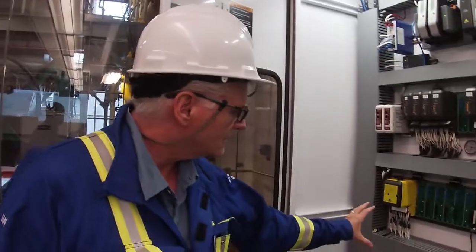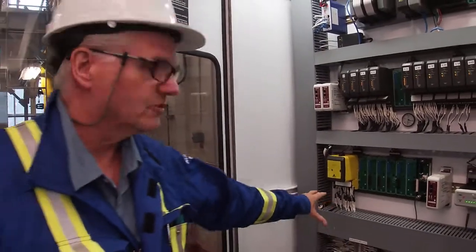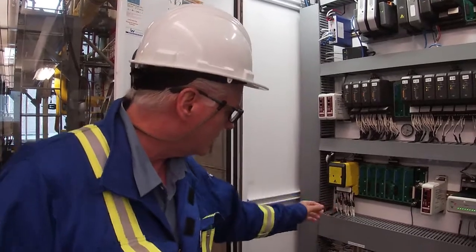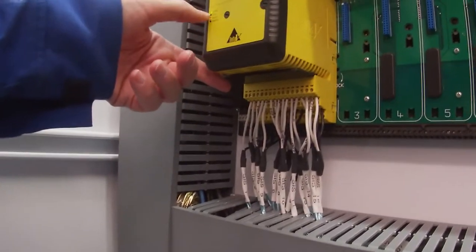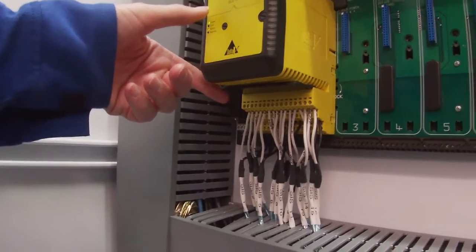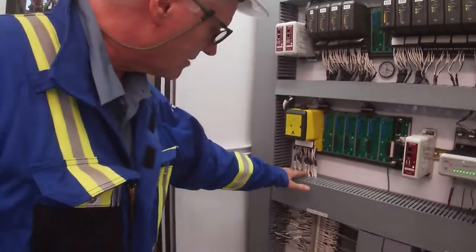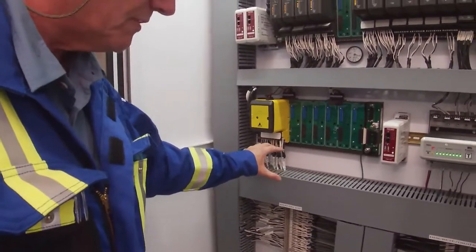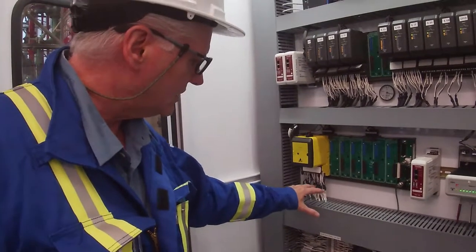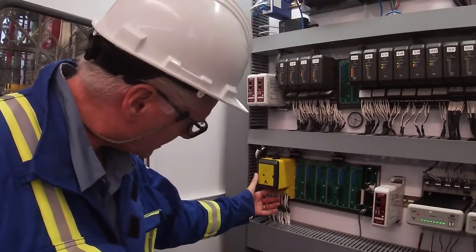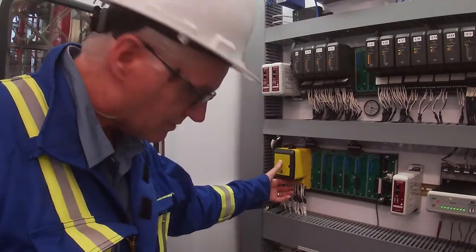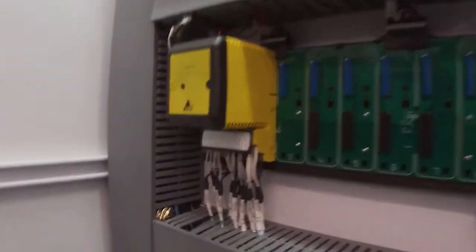So the one nice thing about this SLS module is it's universal I/O. So you just wire into different terminals in here for discrete in, discrete out, and analog in, analog outs. Okay, so we've got them all marked here. So we've terminated our discretes and our analogs, and you can see in our terminations, there's three different levels here. There's A, B, and C in here that we would go into. From there, and it's a little tight in there to wire it in, and that's normal though to have.